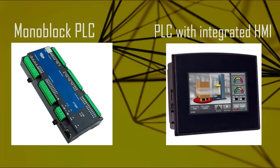Monoblock PLCs. Yes, these are PLC systems where the CPU and I/O modules are integrated into a single unit, as opposed to the modular design we just discussed. Monoblock PLCs can be more compact and may be a more cost-effective option for simpler applications. They can also be easier to install and set up, as there are fewer components to connect and configure. However, monoblock PLCs may have less flexibility and expandability compared to modular systems, as the number and type of I/O modules are fixed.